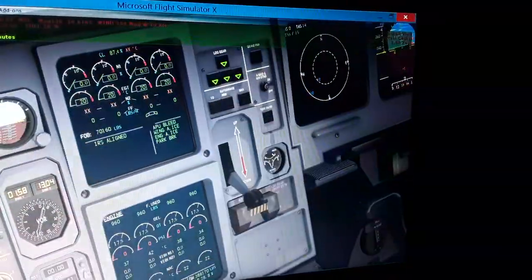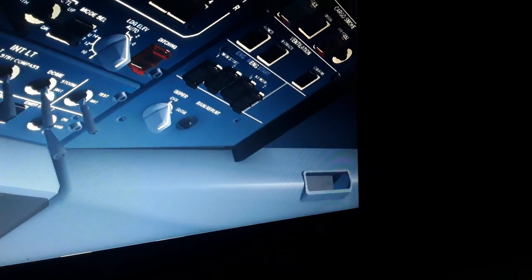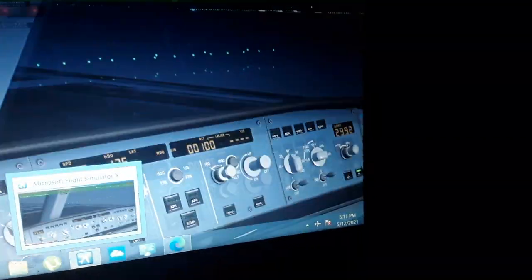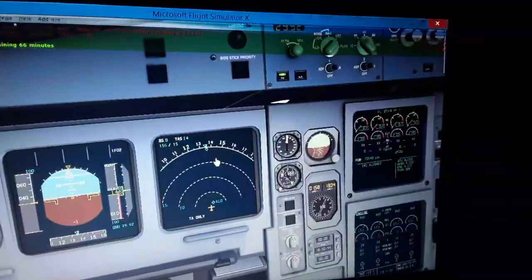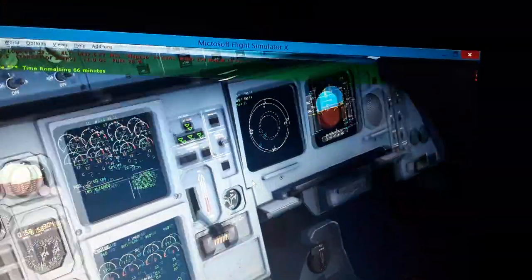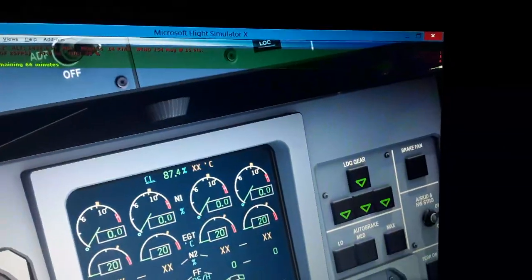This is gonna change a little bit with engine starting, so I'm gonna use the engine start selector maybe. Need some dome light. I'm gonna select here. This is the engine mode selector over here. We're gonna use the ignition start position. So this is going to initialize some systems.